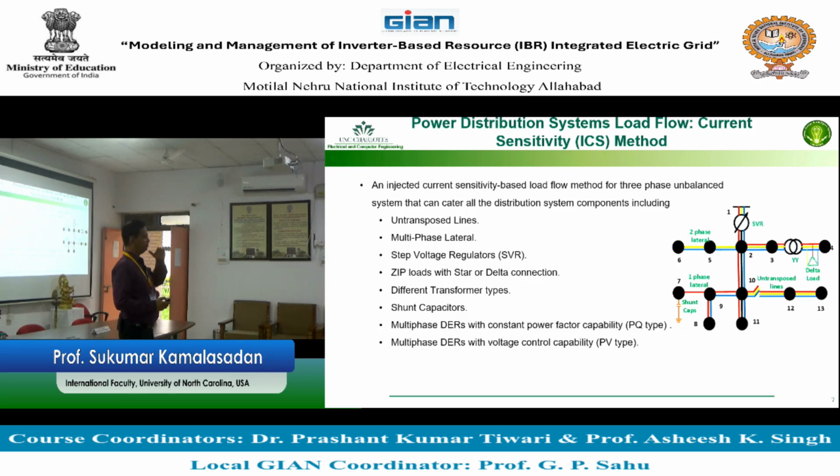So it is going to be just staying there, pushing the power from sunlight or whatever to the electric grid. Such a model of a DER is called PQ type. It's also called negative load model, which means if the load power is positive, you see the power from the inverter, or the power from the PV farm, is negative. So this model will be used also to represent what we call a net load.